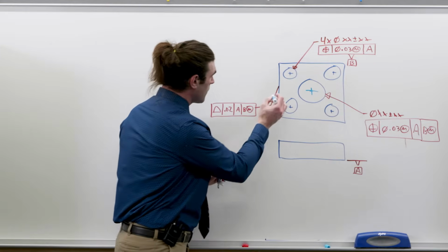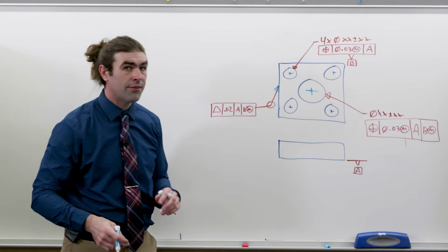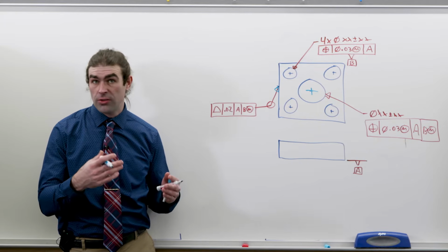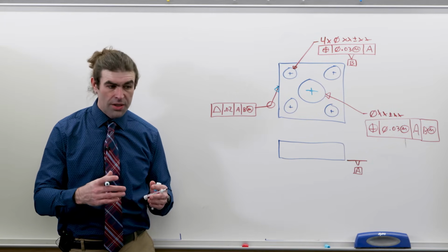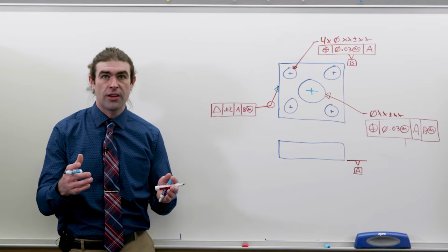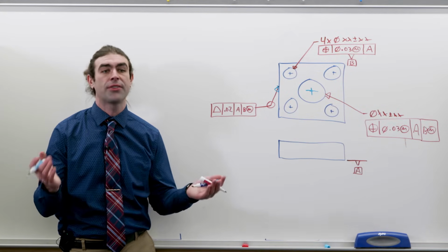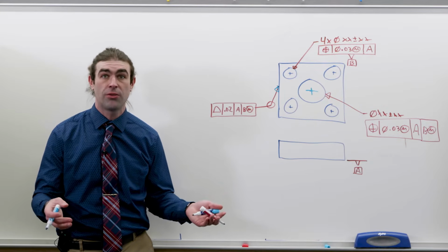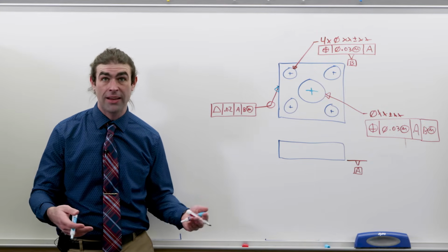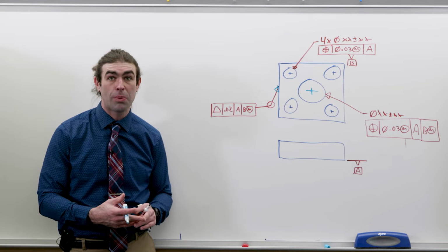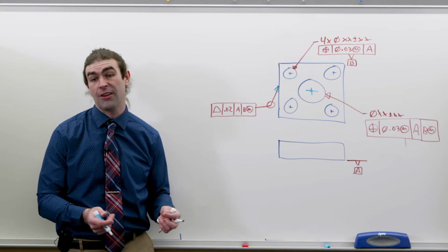This is great if the outside of the part mates to air, which just means that there's nothing it's going to touch at assembly. So you could think of the outside of a television screen mates to air. A lot of things mate to air, and you want to be sure to give that kind of stuff as much tolerance as possible because it's not functionally very important.